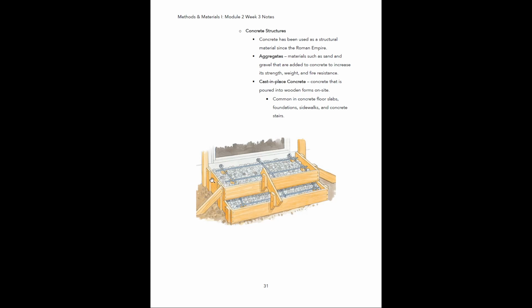They will build up these wooden forms, and then they will fill that with some crushed gravel, and then this right here is actually rebar. This metal wiring that's running through there is to add some structural integrity to the concrete itself. But once they have all this in place and they have the form built, they will then pour the concrete in and let it dry and cure, and then you'll have your finished steps. But that's what they mean by cast in place.